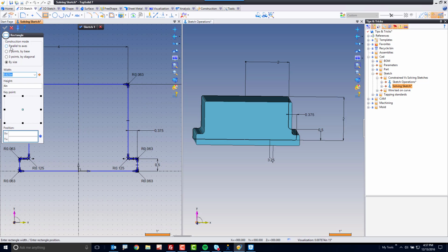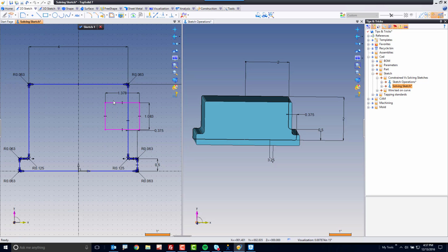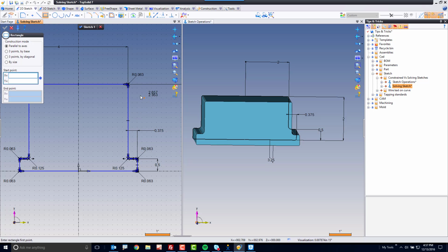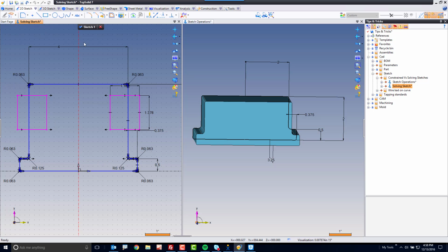Now check it out. If I go here and just make a little rectangle, like so, notice it didn't automatically mirror. That's fine. Maybe I need to turn on symmetry. So let's go back and turn on symmetry about orthogonal Y. That's fine, and I can go ahead and make my rectangle like that. And of course, this time it did mirror. But even if I leave this on, it doesn't matter.